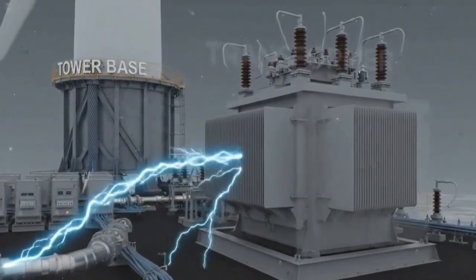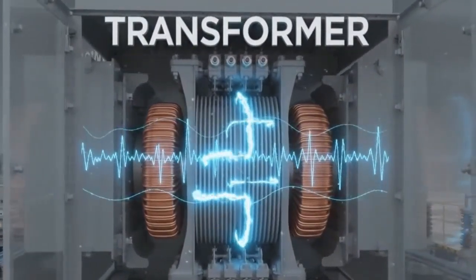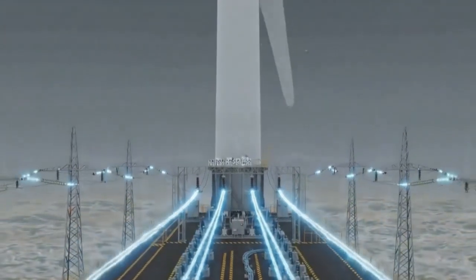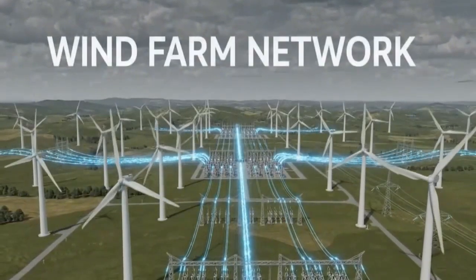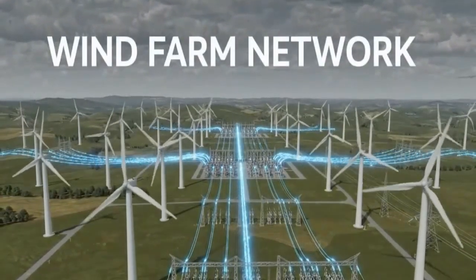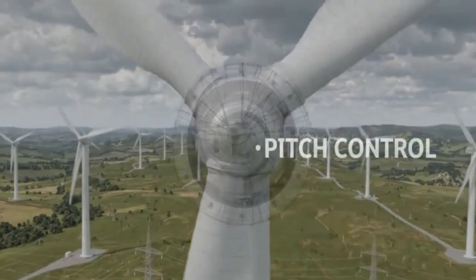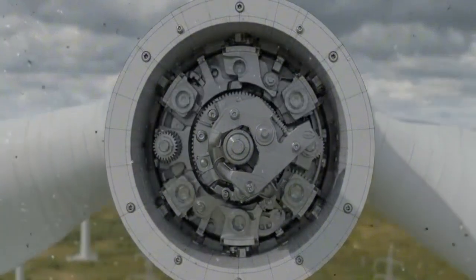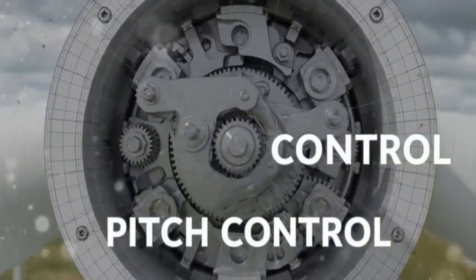However, the electricity produced can vary with wind speed, so it is not always ready to go straight to the grid. The power converter processes the electricity, adjusting its waveform, voltage, and frequency into a more stable output. After conditioning, the electrical power is better suited to travel through the cable system inside the tower.